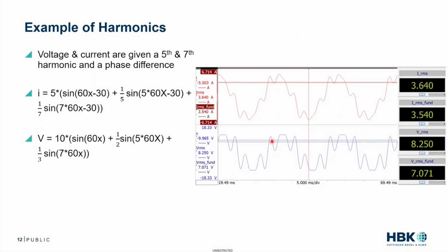All right, so let's look at an example. Again, this isn't switching harmonics yet, but this is a practical example just to instill these points. So I'm taking another current and voltage that I've manufactured in our software just for example's sake, so I can operate in the ideal realm. My current's fundamental frequency has an amplitude of 5, and I implement 5th harmonic and 7th harmonic with a given amplitude.